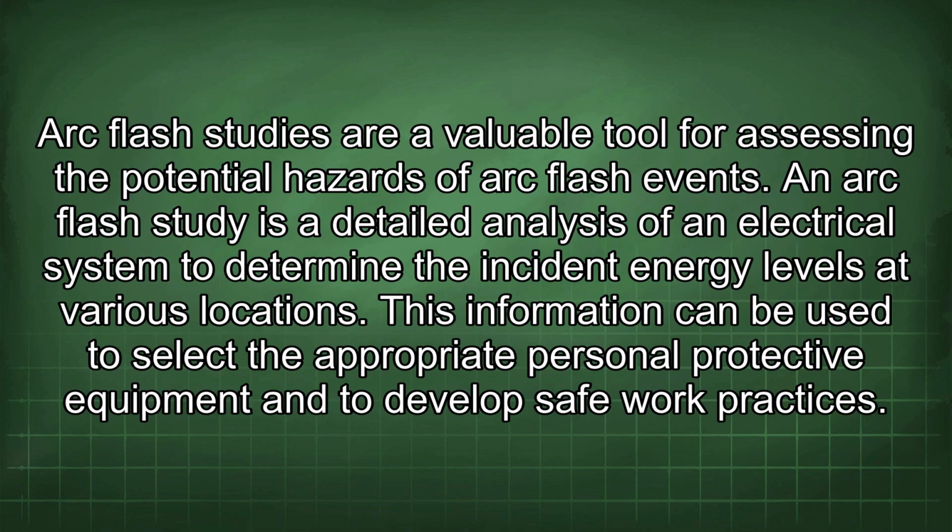Arc flash studies are a valuable tool for assessing the potential hazards of arc flash events. An arc flash study is a detailed analysis of an electrical system to determine the incident energy levels at various locations. This information can be used to select the appropriate personal protective equipment and to develop safe work practices.